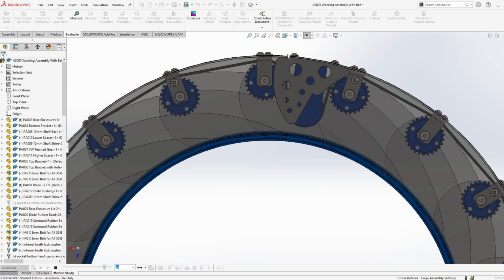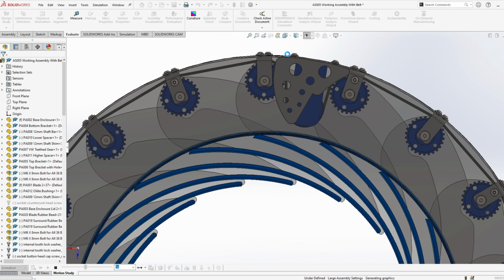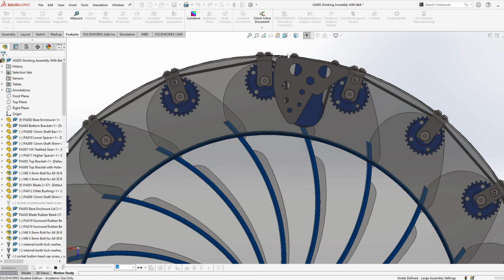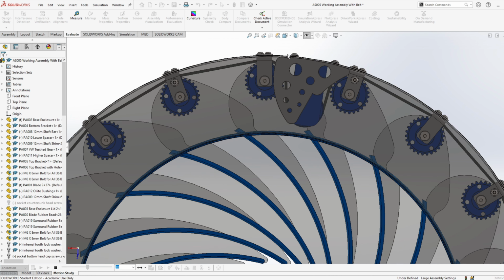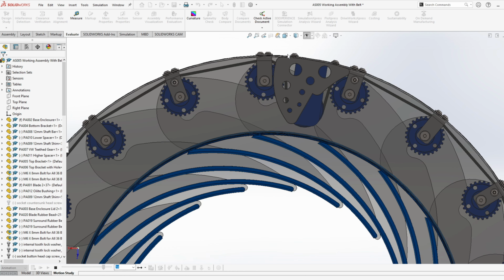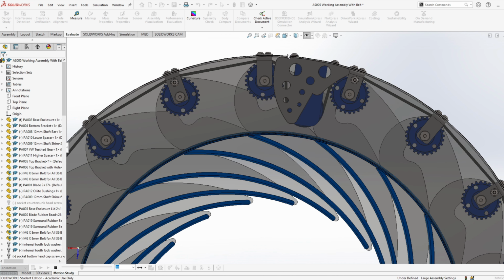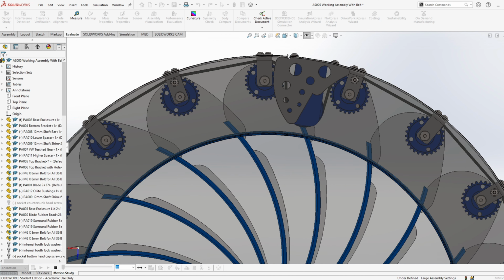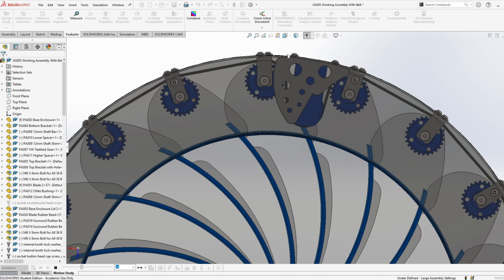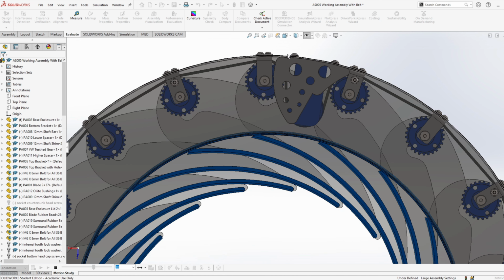Hence, the further we move away from the gearbox side tensioner in theory, the pressure on these far gears will become less. For example, the large circumference of the belt, with all the stress and strains, along with the additional forces, could cause the belt to stretch.